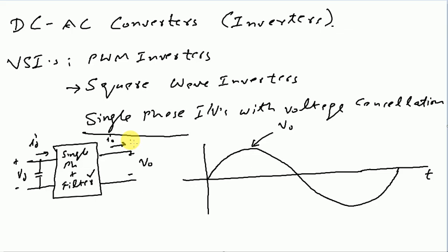But let's become a bit more realistic in this case, and let us say that we do have some practical load, for example an AC motor, in which we will have, of course, a significant portion as inductive. So it will be an RL type of load, not a purely resistive load. It will be inductive for a significant portion, or a combination of resistance and inductance. So this inductive load will mean